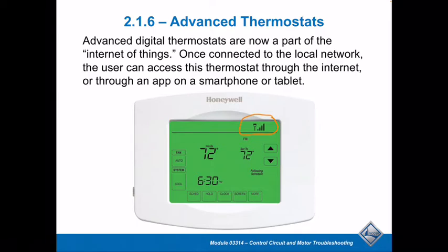Also, line voltage thermostats were actually subject to a condition called thermal offset, and we would refer to that as droop, D-R-O-O-P. The droop would cause the thermostat control point to shift away from the selected set point. Whatever you had for that set point, it would drift away from that, and it would create a bit of a problem with changes in the thermostat and how it's sensing.